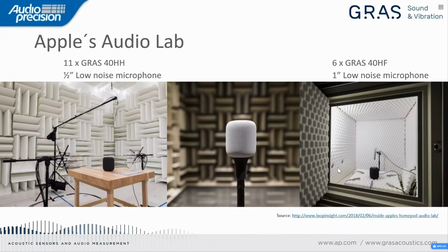But I think it's important from this picture to note that particularly in the first picture, you can see hints of a setup that is based on the ISO 11201. So we have a hemi-anechoic chamber here, and we have the ISO 7779 test table. On this other case, we can see a similar stand that we use for the tablet testing, in this case inside a fully anechoic chamber.